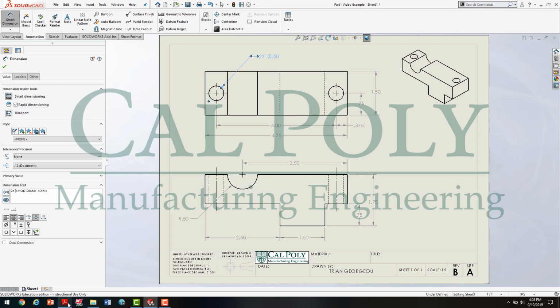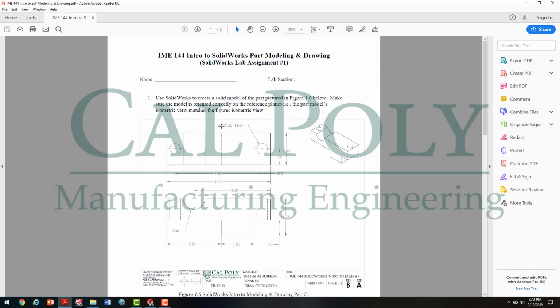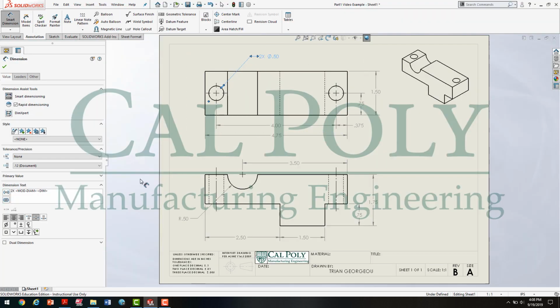Notice the engineering drawing I gave you in the assignment has a space between the X, which really it's 2X and then a space. I added an extra space again. So a couple revisions here or there. But when I move back to SolidWorks, you'll see I've got to add through. So I'm going to click on the dimension, go back to this dimension text, press space and write THRU. Because all lettering on an engineering drawing is an uppercase lettering.